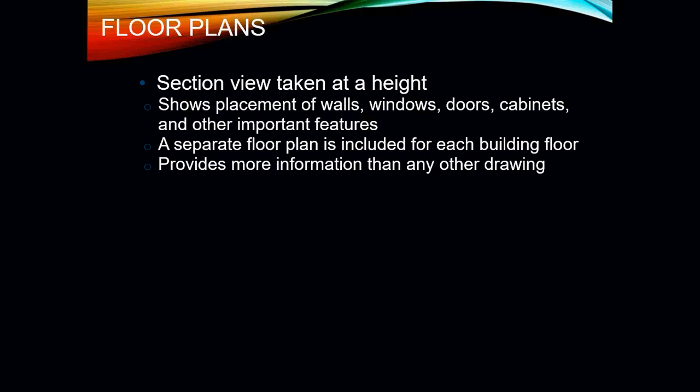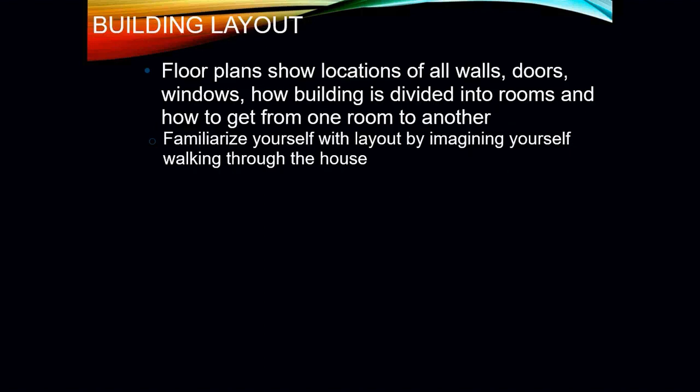Okay, and these also provide more information than any other drawing. Your floor plans, again, are going to show the location of all your walls, your doors, your windows, how the building is going to be divided into rooms, and how to get from one room to another. Obviously, it's going to show you where the door placement is. Okay, familiarize yourself with the layout by imagining yourself walking through the house.